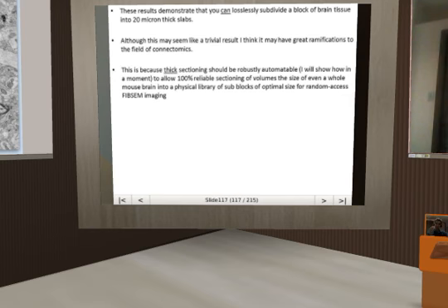If a beam of gallium ions is focused electrostatically so that it comes to about a 10 nanometer beam size, that highly concentrated beam is then scraped across the surface of the block to ablate the top few nanometers of that block.